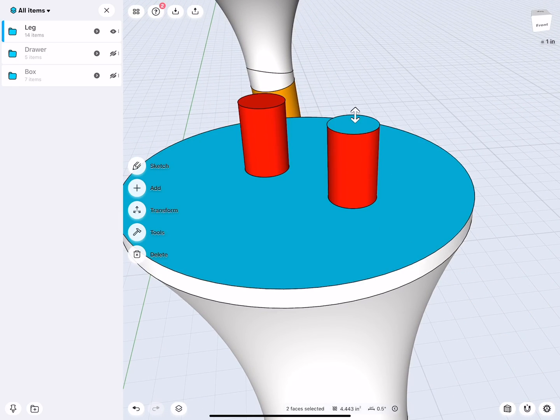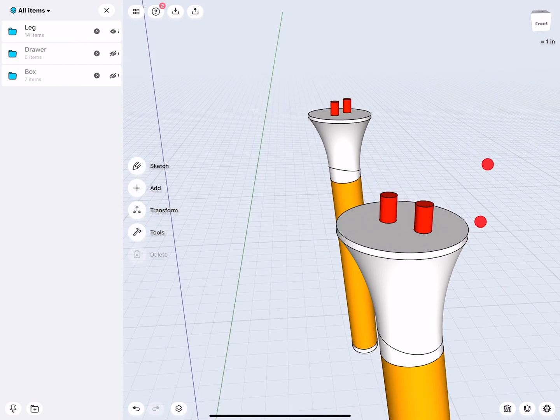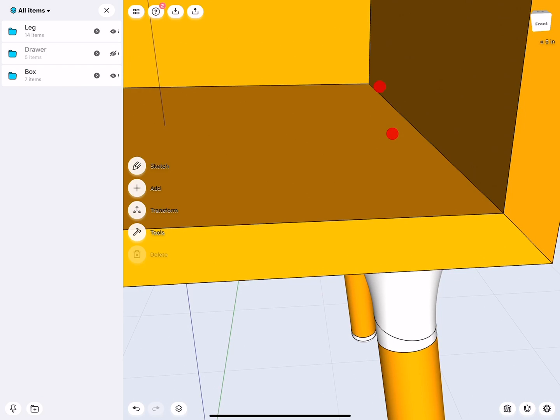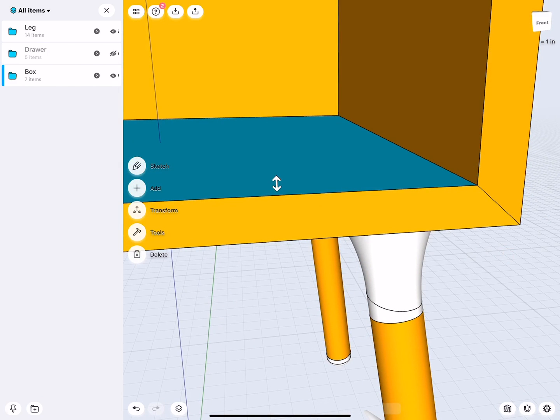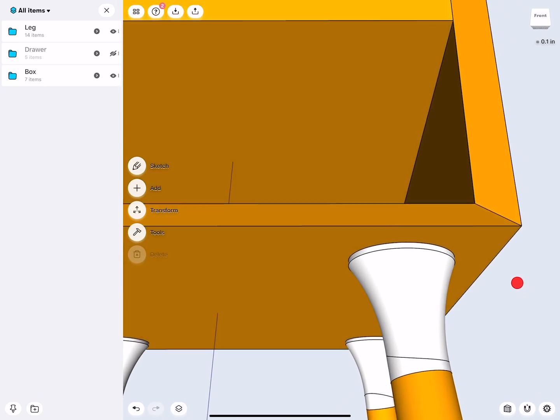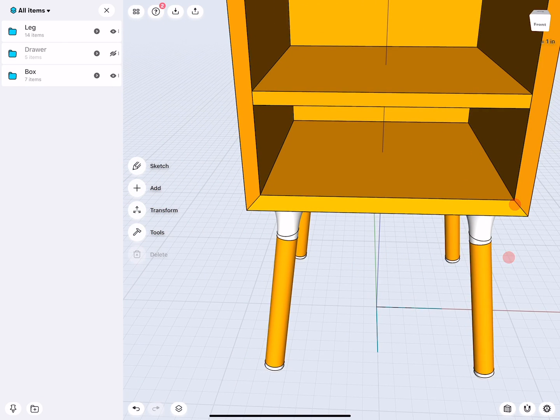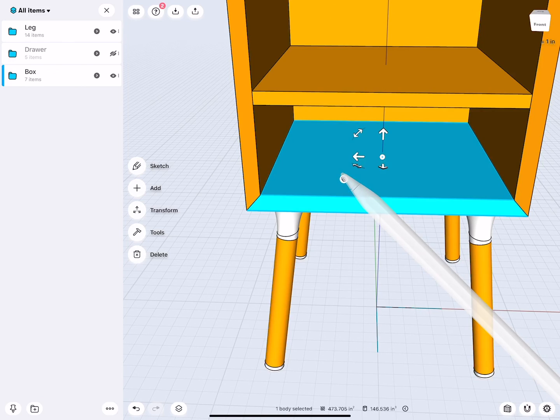The height, you see I selected these two faces, tells me that this red part that sticks out is ½ inch in distance. This is good to know, because when I select this face and this face, it tells me that this is actually 0.7. So I have actually 0.2 inches of material left. That means the dowels are perfectly inside and not too close to the edge of this wooden board.